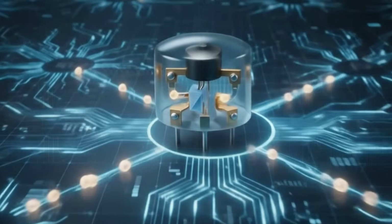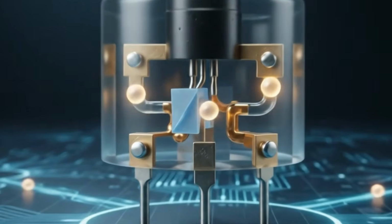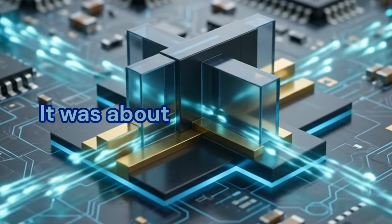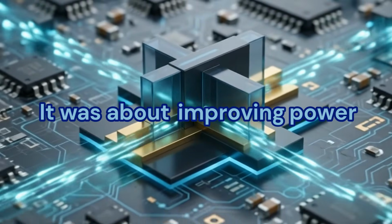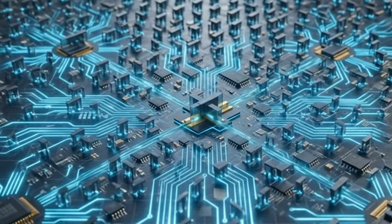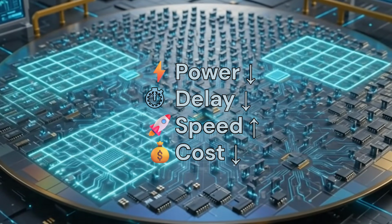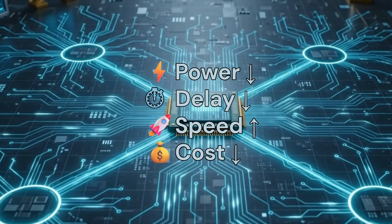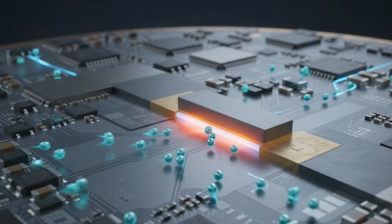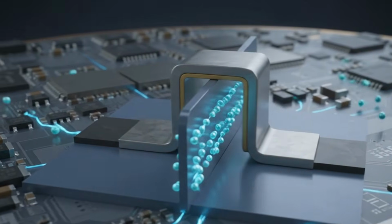Naturally, a question comes up. If older transistors were already working, why did engineers keep making them smaller? Well, shrinking wasn't just about making them tiny for the sake of it. It was to increase the transistor density while improving power, performance and area, while also making devices practical for real world applications. Smaller transistors consumed lower power, reduced switching delays, allowed faster operation, lowered cost per function. So, the ability to continuously increase transistor count per area while improving performance became the driving force behind transistor scaling.